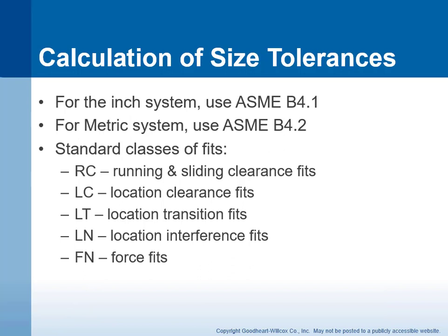Now let's talk about calculation of size tolerances. Anytime you have parts that fit together, like a wheel that fits on a shaft, for instance, you can classify the tolerances of the fits. When I say tolerance of the fits, I mean that a shaft has an OD with a tolerance, and then you have a wheel that has an ID with a tolerance. And then these would be the classifications of fits.